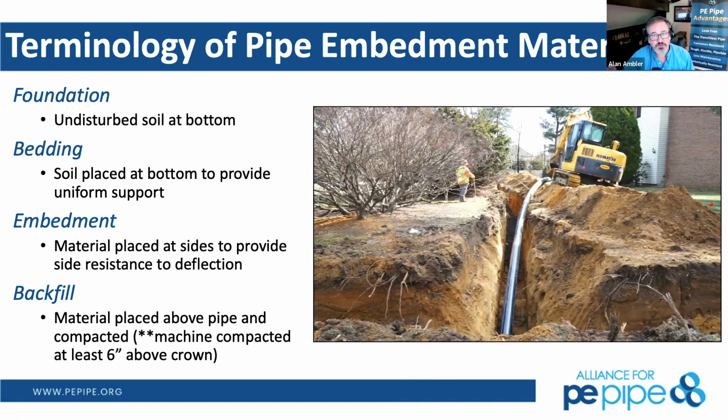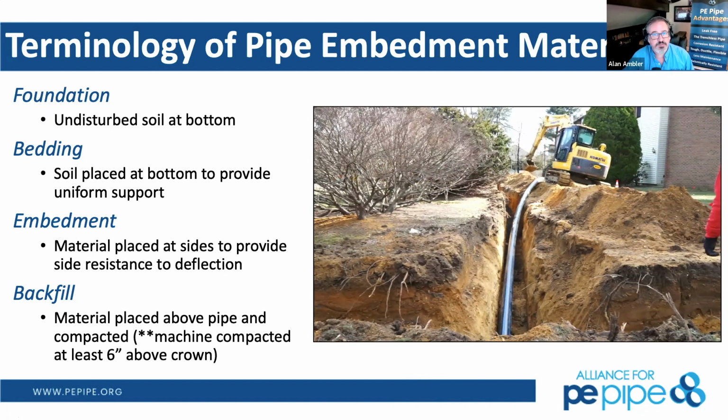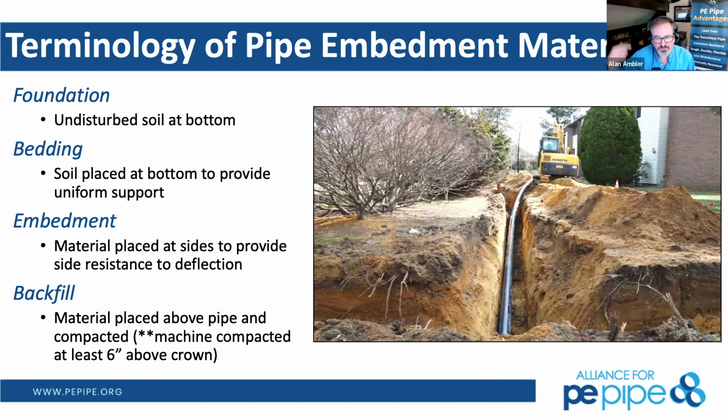You're not seeing that portion of it, but then there's embedment and backfill that's placed on top of this pipe. This is in a clay native material. It doesn't look like there's going to be a box truck loading on it. One of the reasons why I love to point this video out is the fact that there's nobody in the trench. You don't have to get in there to secure the bell and spigot or make the connection to a valve. Obviously, there'll be a larger excavation on the other end when we're tying it into place, but it's safer for the employees by not being in the trench in that manner.